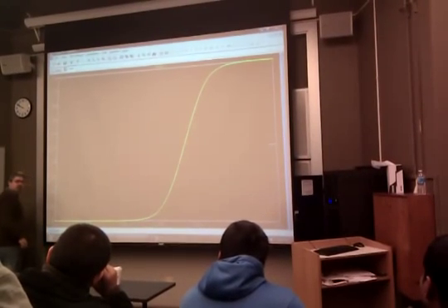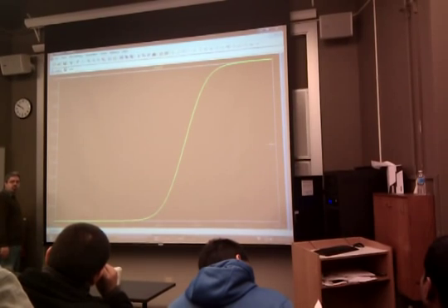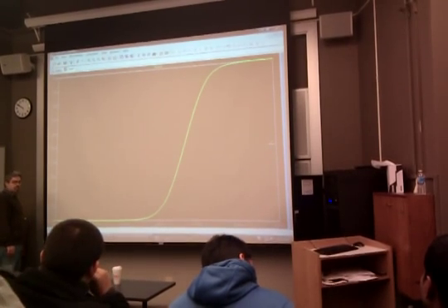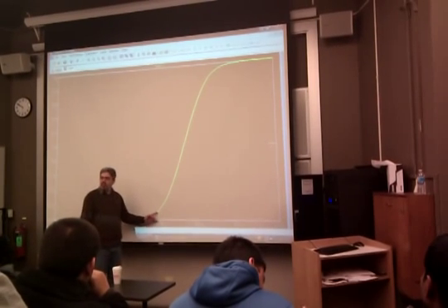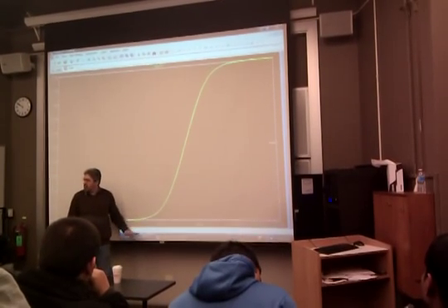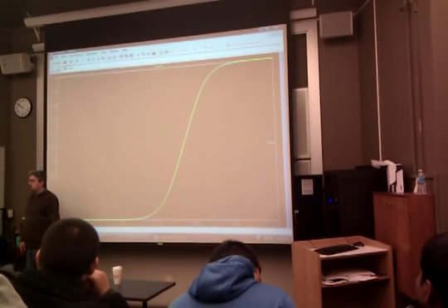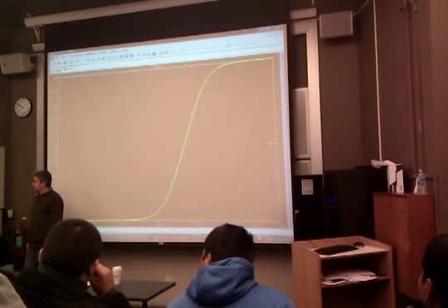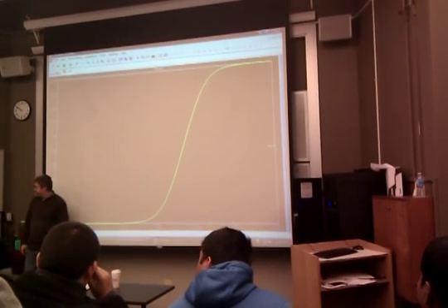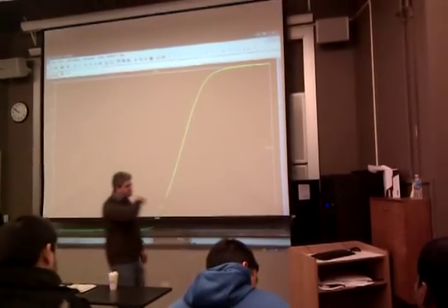The frequency points are in hertz, not in radians per second. But if you made the conversion, you would see that they're right on. Except that at the corner frequencies, we're off by 3 dB from the straight line approximation that we think. Yeah. You can't do it on this one because we didn't do DC now. But if you look at the surface that we have up there, you will see